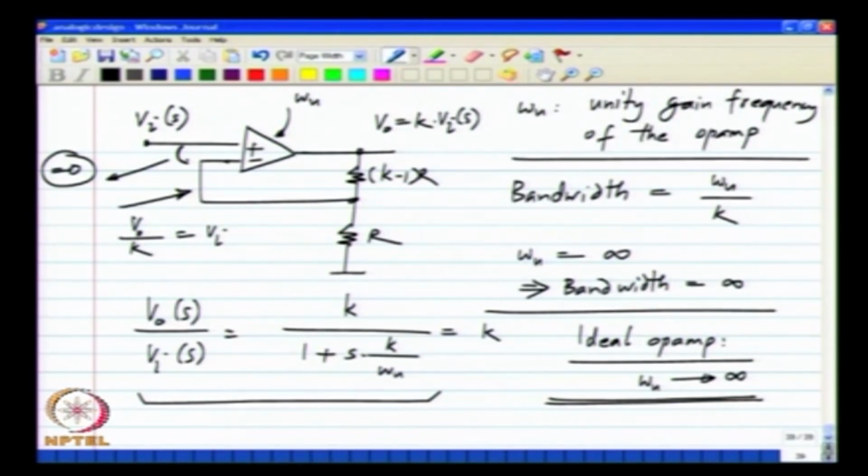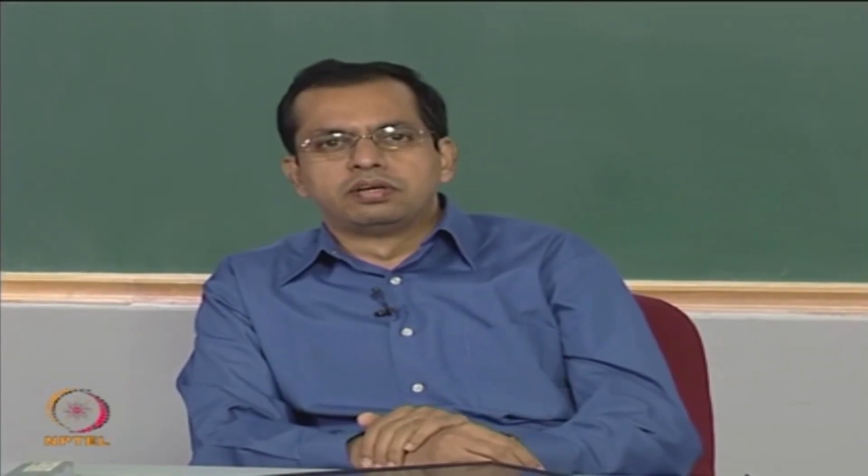For that we see that we need a block that senses the difference between two quantities and something that integrates the difference, and we can arrange it as a negative feedback amplifier. So, that is an amplifier in which the error is gradually driven towards 0. Okay. So, such a block, when you have an integrator, behaves ideally when the input is constant. When the input is constant and you wait for the output to reach steady state, the error or the difference that is sensed will eventually become 0. Okay. In steady state the error will be 0.